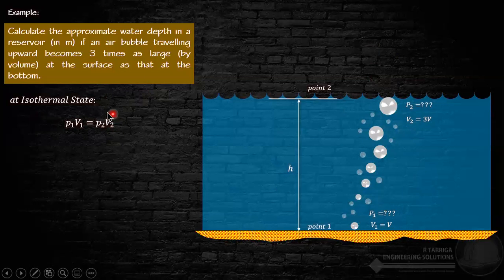Okay. Remember, within this formula, the pressure must be in absolute state. Okay? So, I will just insert this. This is for the next topic, sana, but anyway, this is very important in this solution. Remember that absolute pressure is equal to gauge pressure plus atmospheric pressure. Okay? The atmospheric pressure is the pressure in the atmosphere. Okay? The standard is 101.325 kilopascal or 14.7 PSI. So, if you want to get that conversion, you can search it on Google.